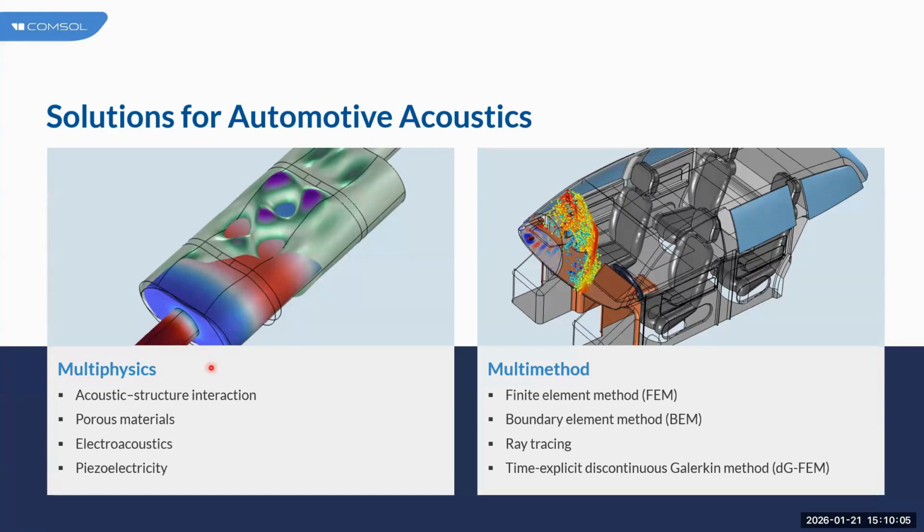And when you are modeling these types of vibroacoustic problems, you might require modeling porous material, which is widely used to reduce noise. It can be porous materials to model the floor carpets or roof linings, seats or door panels of your car or vehicle. It can be used in mufflers and particulate filters as well. You can see a screenshot of an example of an absorptive muffler, which also uses a porous domain. Glass wool is used as a porous domain here to reduce noise.